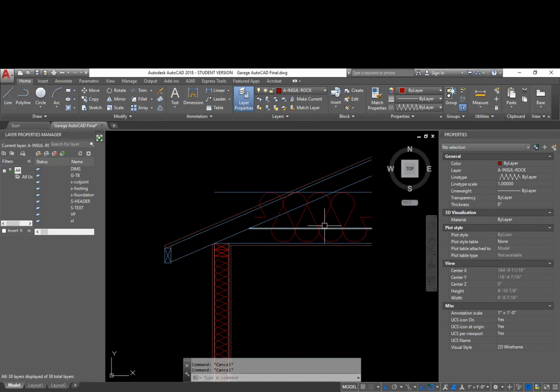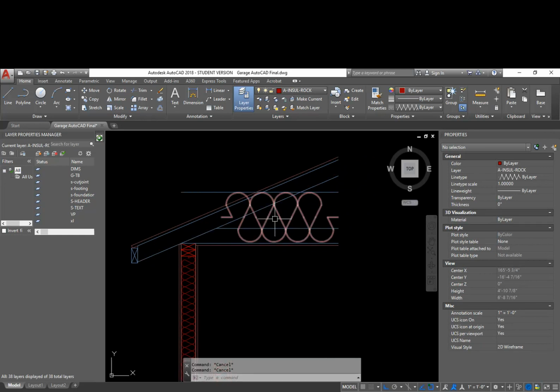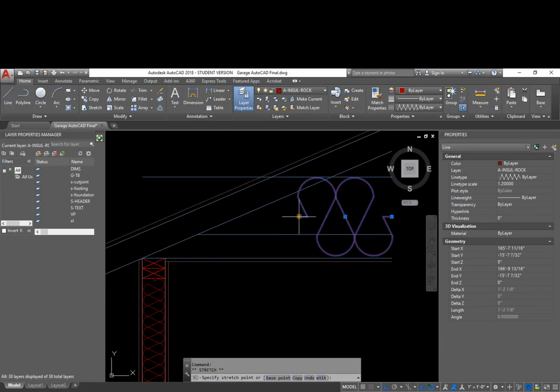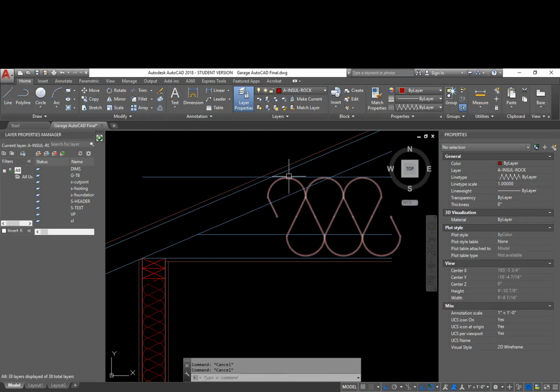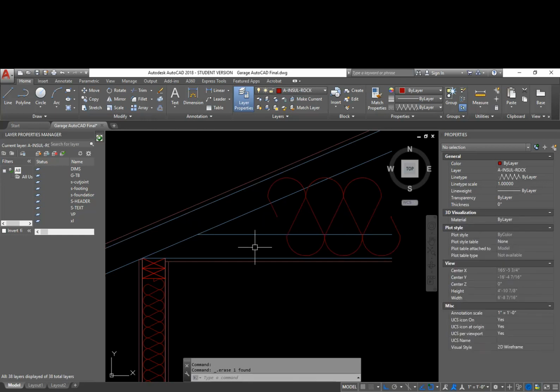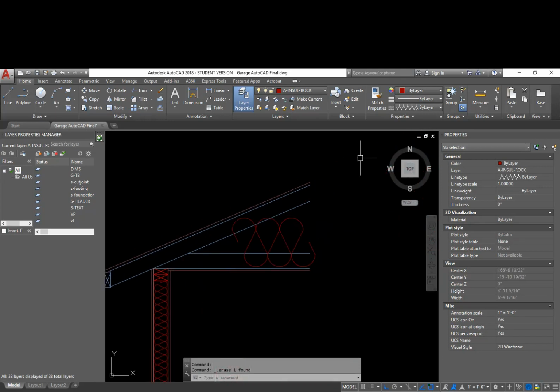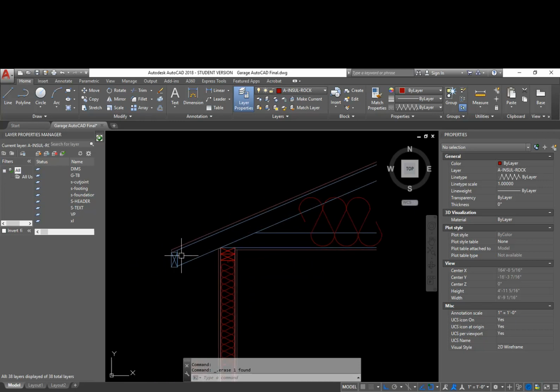So the real problem in real life is, if I'm going to use a 12-inch bat up here, I'm basically going to have to end that bat somewhere back here, because it's not going to go past out from the roof. So in here I have to start compressing it and stuffing it in there, and a lot of times what happens is I have the vented soffit out here, and I have a ridge vent up here, and there's supposed to be air movement that goes through this truss cavity the whole way from down here up to the ridge vent to keep this roof cool at all times,